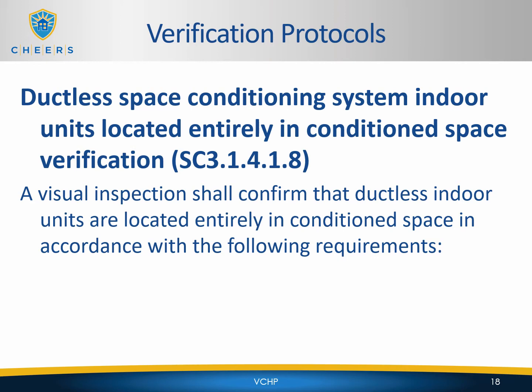Ductless space conditioning system indoor units located entirely in conditioned space verification. Now this one sounds very much like the one we just covered. That was ducted units, duct systems in conditioned space. This one is just the ductless space conditioning system indoor unit. So that indoor coil, fan coil, air handler, whatever it happens to be, is going to need to be located entirely in conditioned space.